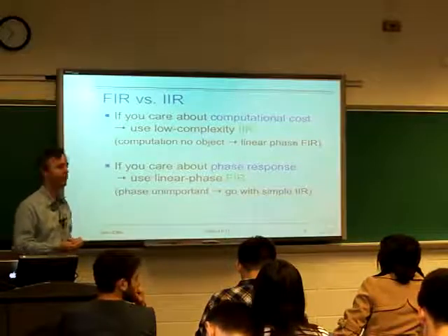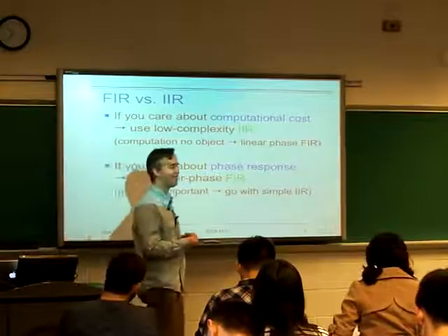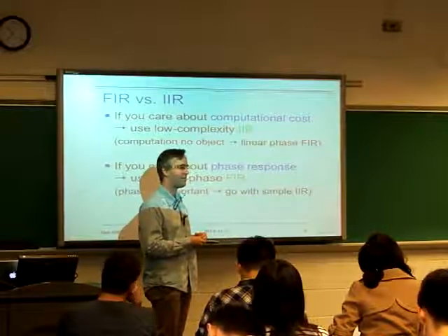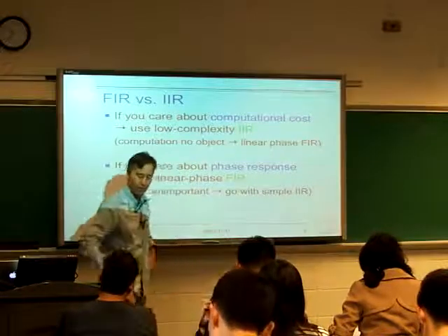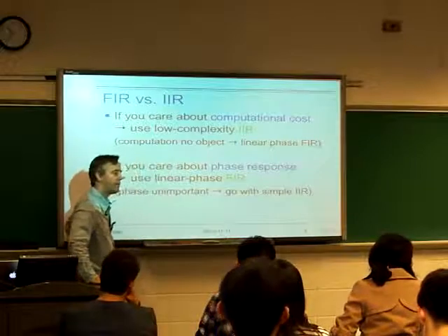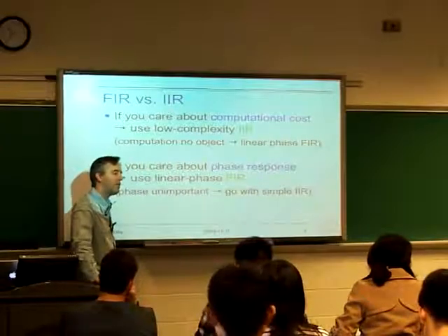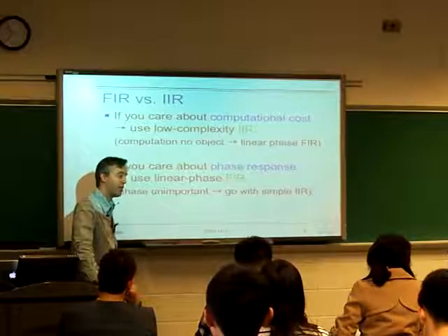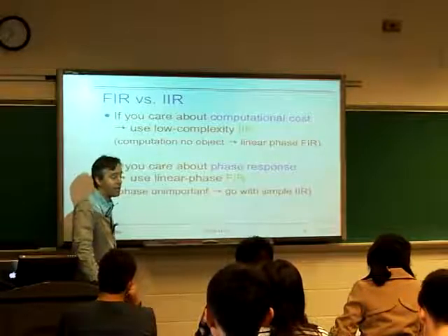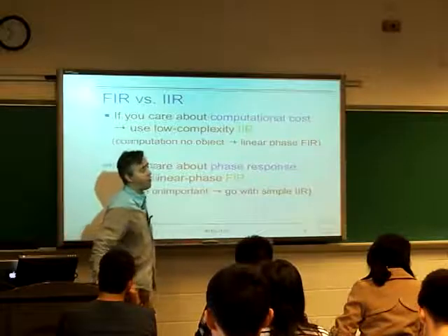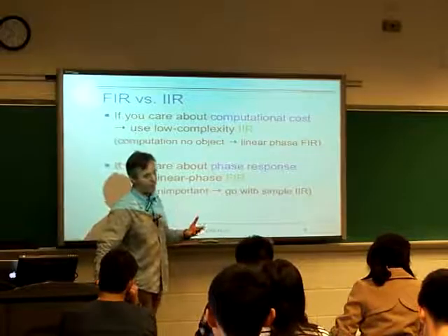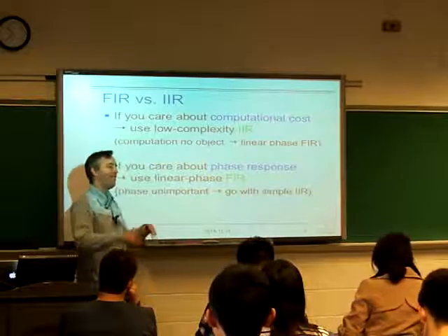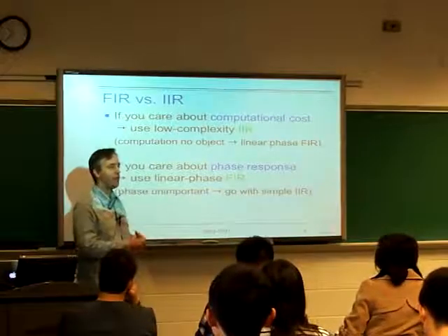Can you please list the applications of filters without linear phase? So if the phase is not linear, then there is distortion. Right. So why would you ever want to build a filter with phase distortion in it? Because it seems like you're just messing up your signal. But although phase distortion is messing up your signal, it's bad news. Typically, it's not terrible.